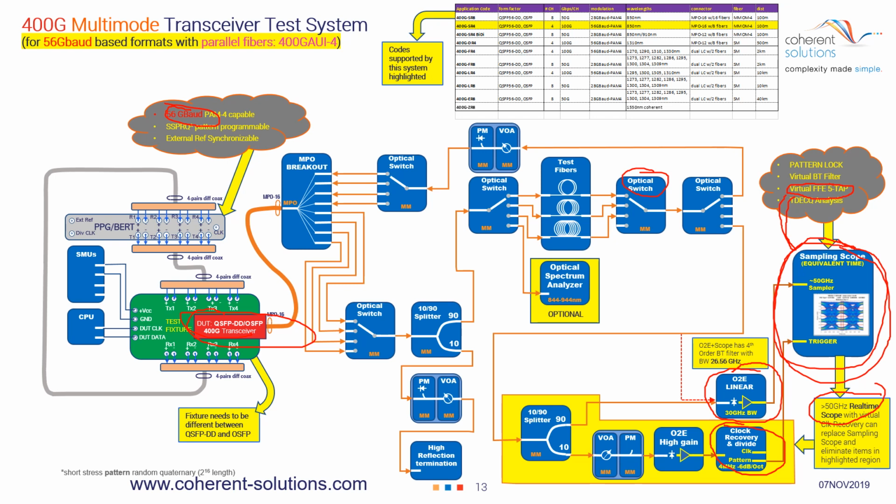You'll also notice a term here as TDEC analysis. TDEC-Q is a new standard of testing that is slightly different from our traditional eye pattern. The important thing to know is that you have to have these software filters for 5-tap built into the oscilloscope, as well as the capability to analyze PAM4 signals.